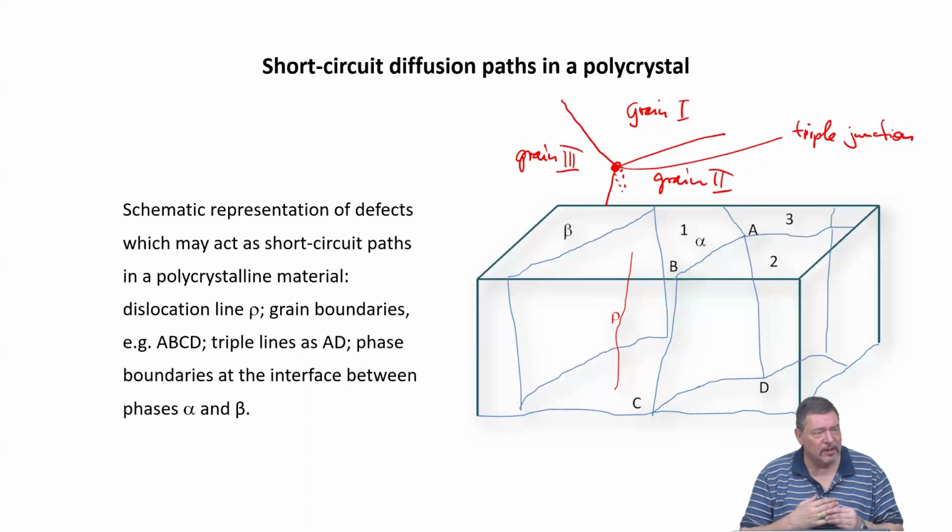But also these are important microstructural elements, because the triple junctions basically govern how grain growth and coarsening would happen, because they basically need to move out in order for one of the grains to become larger. And often these are the pinning points for the grains because of segregation of impurities inside of the triple junctions, and so they basically create what we call a Zener drag. So it means that impurity atoms are going to the defect, find energetically low-lying positions, and so it's requiring a higher activation enthalpy to move these atoms out of their current position.